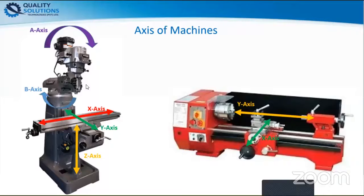In case of the 4th axis, the A-axis, the spindle or the head of the milling machine is able to tilt downward or upward about this specific pivot point. This head is also able to rotate toward the left and right about these axes. We can see a silver scale with markings of degrees, which shows how many degrees we have to rotate this spindle about this specific axis. So these were the manual machines and the axes in those manual machines.